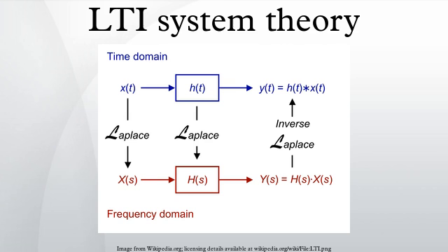The Z transform is usually used in the context of one-sided signals, that is signals that are 0 for all values of t less than some value. Usually, this start time is set to 0, for convenience and without loss of generality. The Fourier transform is used for analyzing signals that are infinite in extent. Due to the convolution property of both of these transforms, the convolution that gives the output of the system can be transformed to a multiplication in the transform domain. That is, just as with the Laplace transform transfer function in continuous time system analysis, the Z transform makes it easier to analyze systems and gain insight into their behavior.